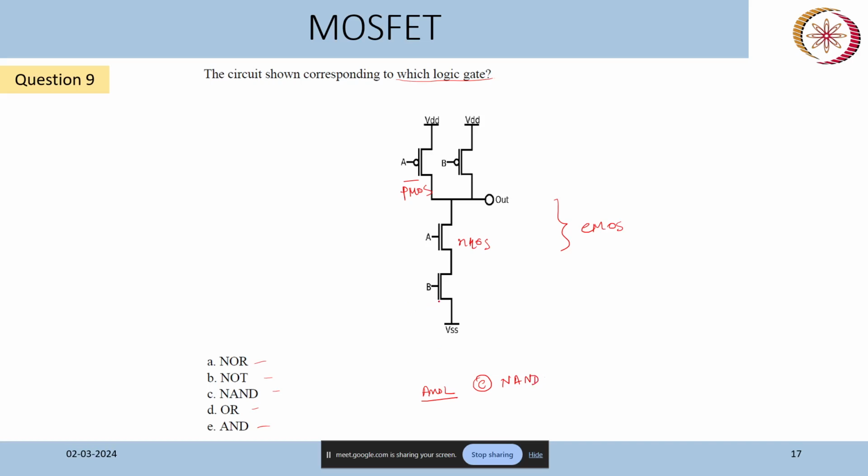So you will be able to draw based on this concept an OR, NAND, or any other gate. If an inverter is connected at the output of a NAND gate, then it will be an AND gate. So if we connect an inverter here, this will be A dot B. Similarly you can make all other logic gates.